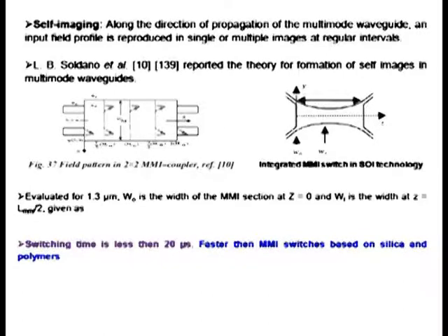This is how in multi-mode interference structures, when power enters from one port, after traveling a specific propagating length, it divides into two equal paths, and again after traveling a specific propagation length, it combines and goes on to the other port, and again it divides into two equal parts, and so on it propagates through the coupling length. And by selecting the coupling length, we can always make it a switch.